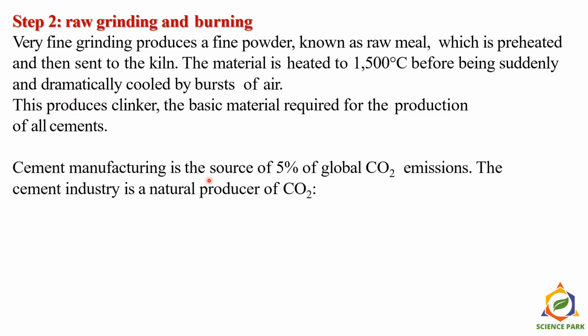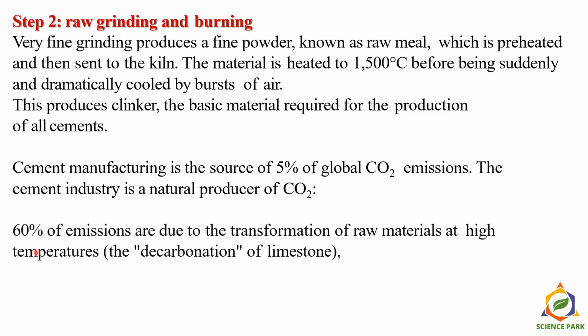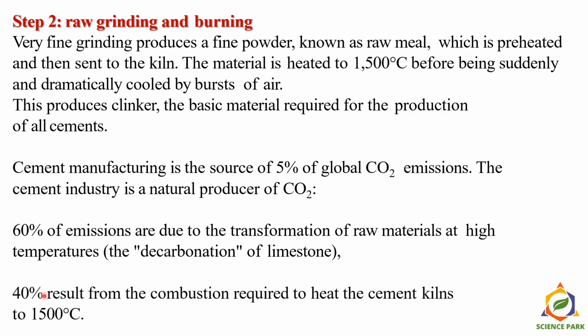Cement manufacturing is a source of 5% of global carbon dioxide emissions. The cement industry is a natural producer of carbon dioxide. 60% of emissions are due to transformation of raw material at high temperature. This process, which produces 60% of the carbon dioxide emissions, is called decarbonation of limestone. 40% result from combustion required to heat the cement kilns.